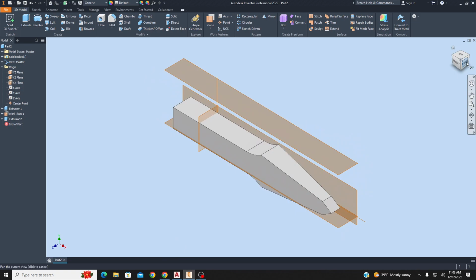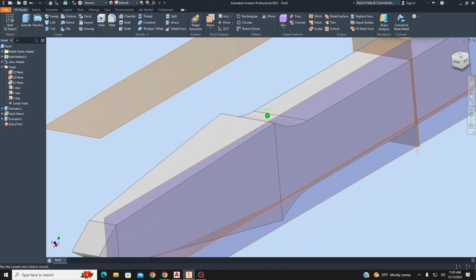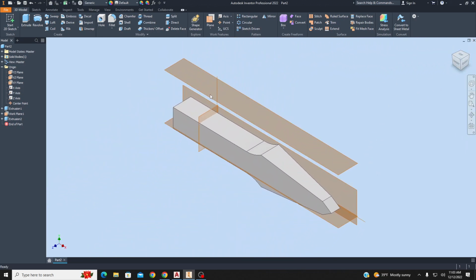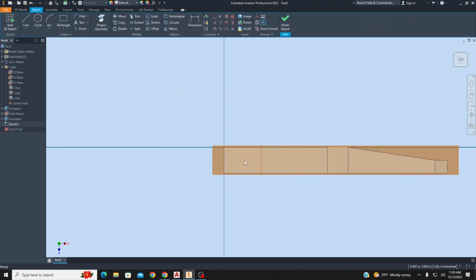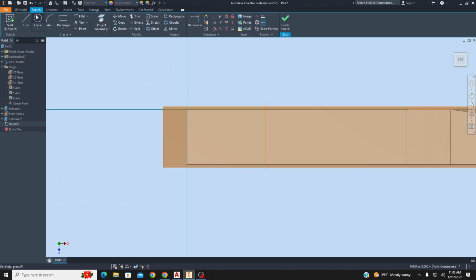F6. And now if we look at the front of our chisel, we can see that tapered face. Okay. There we go. So one last part of the chisel here. We're just going to click on the top face here. And we're going to add that 5/8 radius on the end. So we're going to draw a center line here. So construction line, find the middle of this edge, draw that out,